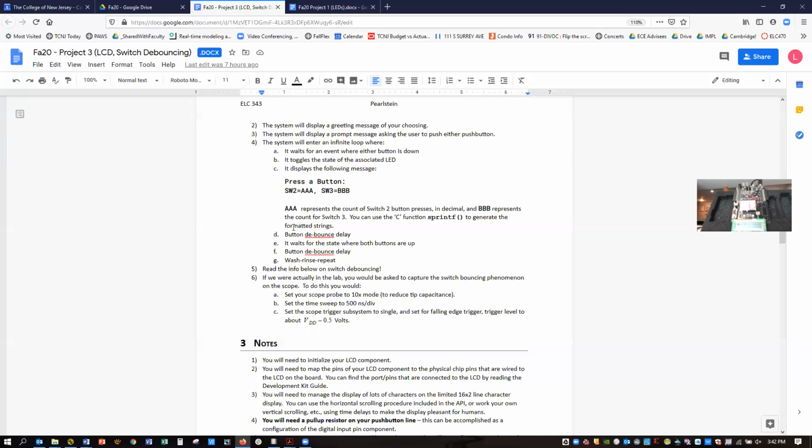Of course, in software, you'll always read a 1 or a 0, but inside the hardware, you can actually get non-binary levels. And switch bouncing can be a hassle. You may have seen keyboards where occasionally one button creates multiple unintended presses. Well, the challenge here is to make sure that each time we push the button, it only gets viewed as being pressed once. And the key to that is, as soon as we detect the button down, either button down, we immediately take the action to handle that button down request.